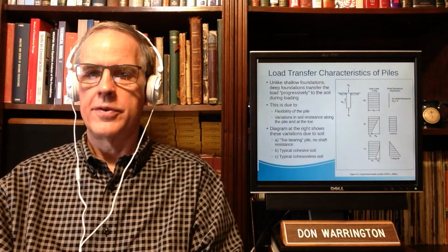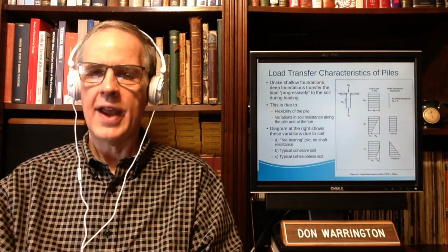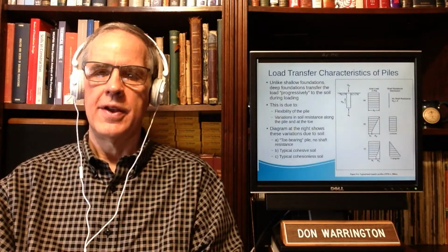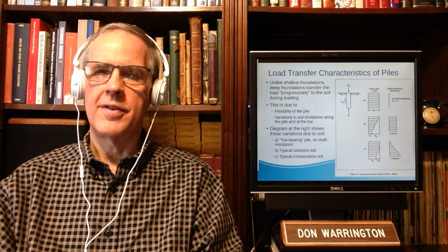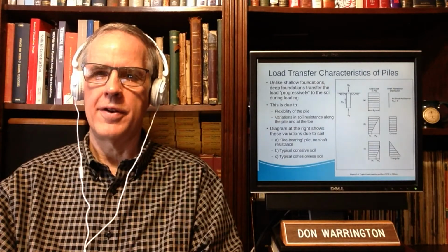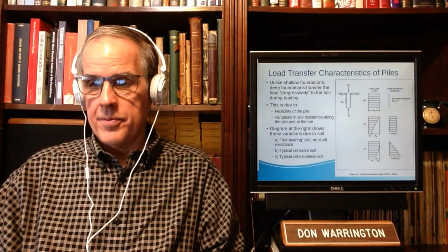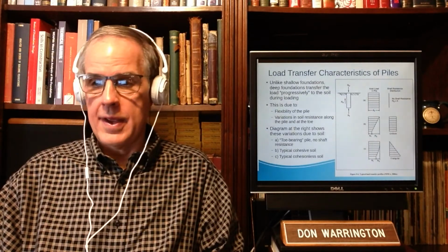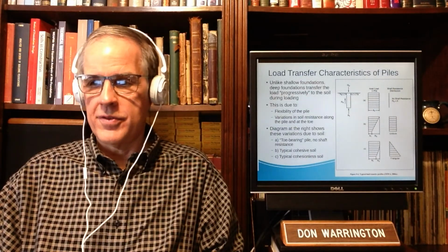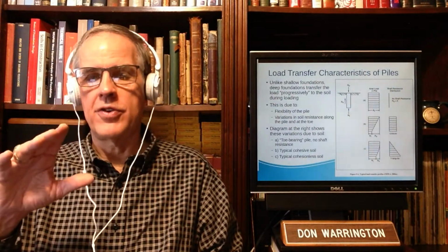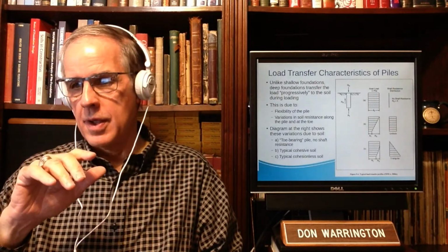Load transfer characteristics. Unlike shallow foundations, deep foundations transfer the load. Actually, shallow foundations do. It's just that our theory doesn't really take it into account. The other thing is the progress is a little bit faster with shallow foundations. No, it's a lot faster with shallow foundations. I'll take that back. It's due to the flexibility of the pile and variations in the soil resistance. There are different ways of distributing the shaft resistance and splitting resistance between shaft and toe, depending upon the type of pile.